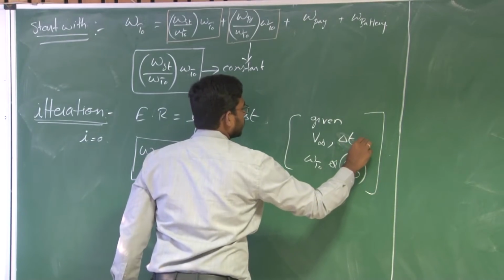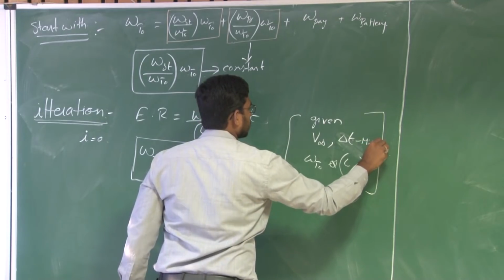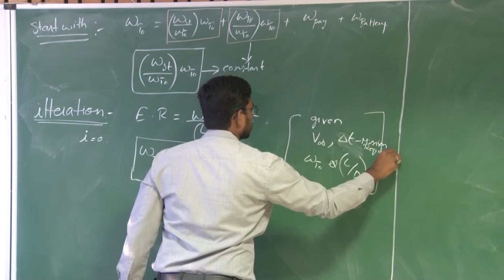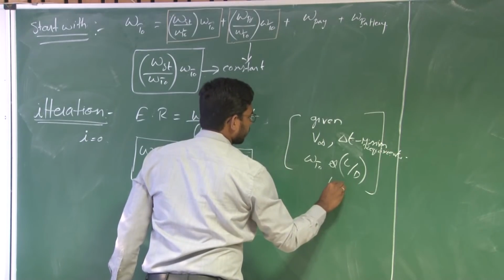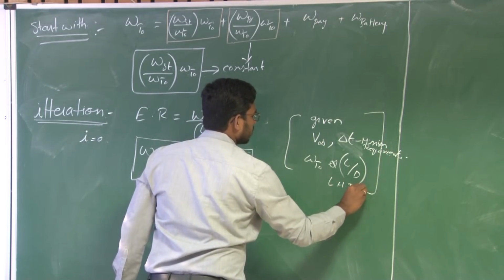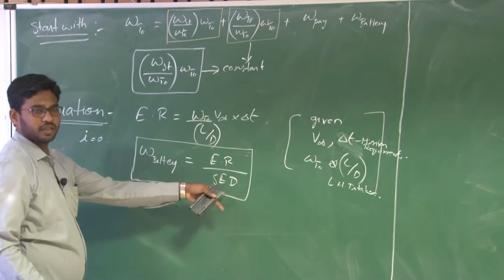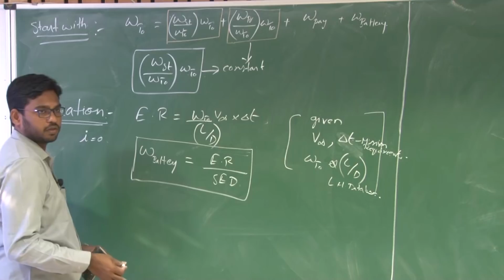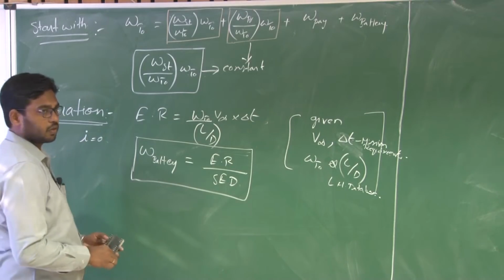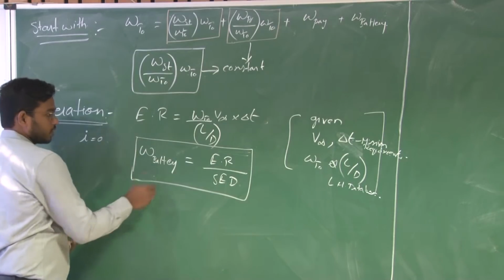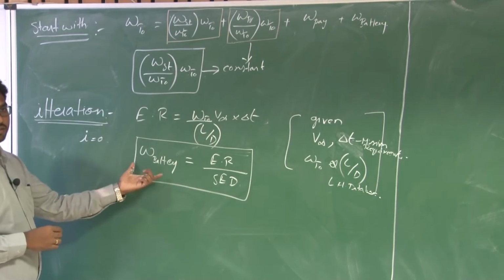SED is from market availability. Do a market survey and find out which specific energy density batteries you can have. So you'll get the battery weight here.